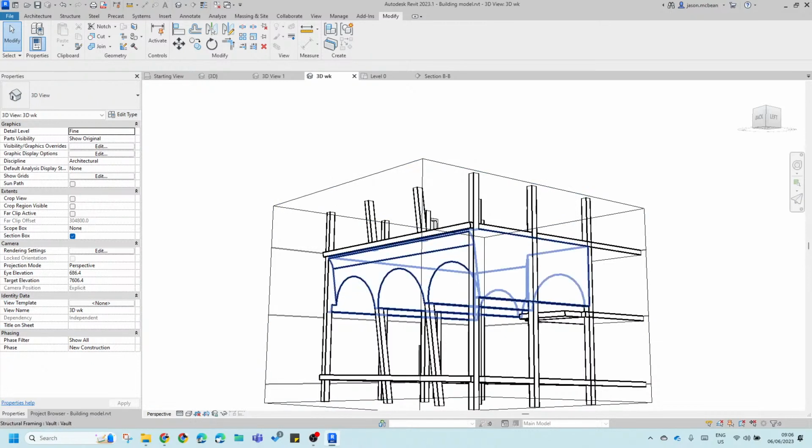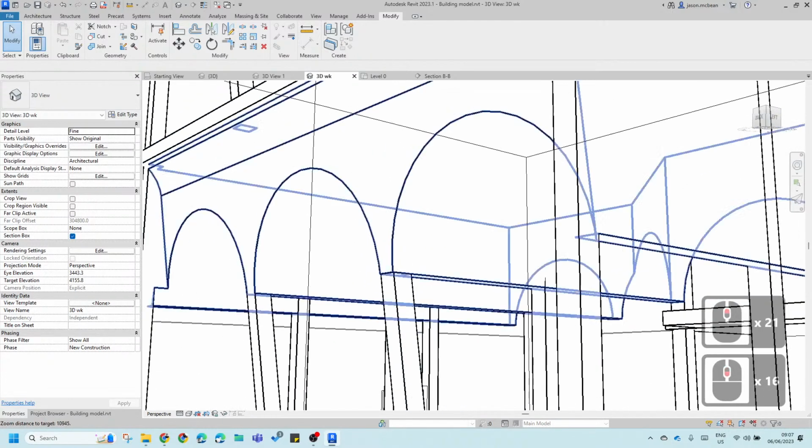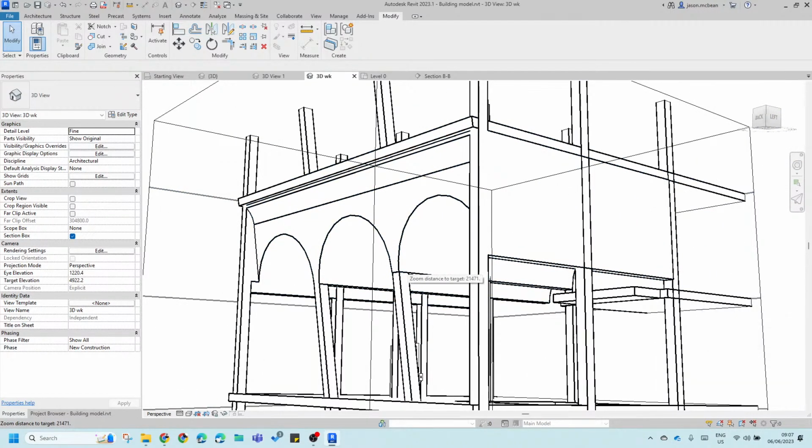What they've done is use a cladding system. It's polystyrene. They pre-mold it, and it looks like concrete, but it's lightweight. They put a material on the exterior which looks and feels like concrete. But is it structural? No, it's not structural at all, it's purely decorative. There are a lot of these cladding systems, and it's literally polystyrene. They build the whole thing out of polystyrene and shape it, then coat it with something very durable against the sun.